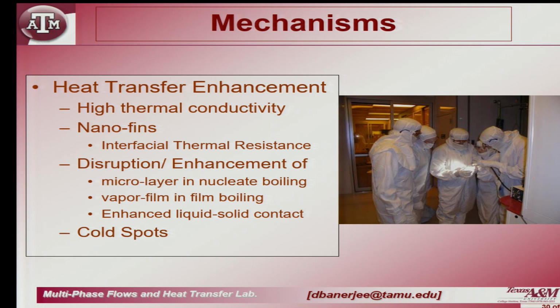right. Now, the question is, and we know this fin is causing disruption of the vapor layer, it might be causing a disruption of the micro layer, we do not know. Remember we talked about the micro layer, where under the bubble you get this wedge shaped liquid that is trapped, and there is a controversy. Some people say it is 1 micron thick, some people say it is 100 nanometer thick, and it is only about 100 microns long, right.